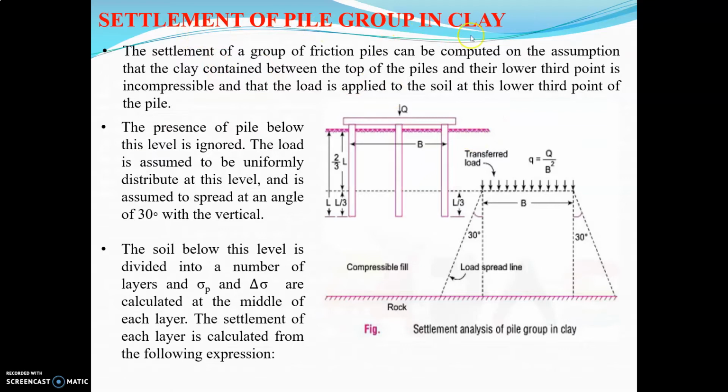Settlement of pile group in clay. The settlement of a group of friction piles can be computed on the assumption that the clay contained between the top of the piles and their lower third point is incompressible, and that the load is applied to the soil at this lower third point of the pile. You can see here, the lower third point of the pile.